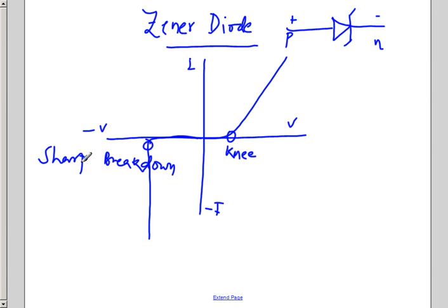What we normally use in a stabilizer, instead of any fluctuation from 220 to 290 volts, this will ensure that a constant voltage is given to our home appliances, which will not damage our instruments. So the Zener diode application can be called a voltage regulator. It regulates the voltage, it makes the constant voltage. The application of the Zener diode is a voltage regulator.